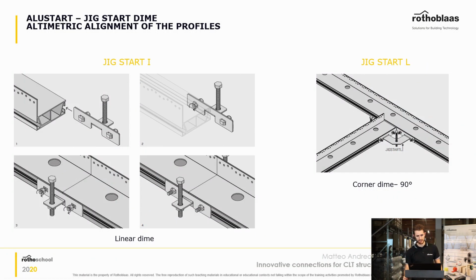These things here are dimes, and they are needed to adjust the height of the Alustart, so that you're sure that you're perfectly aligned with your upper CLT structure. So you completely avoid the issues that you had before with a concrete wall. The tolerances are exactly the same, so you can be very precise with these as well.